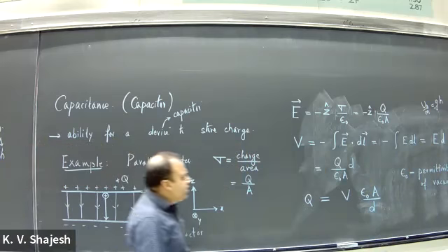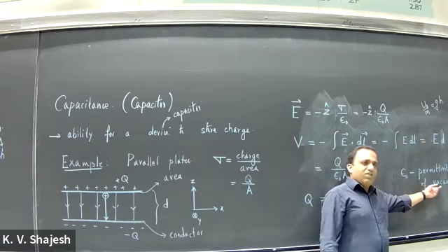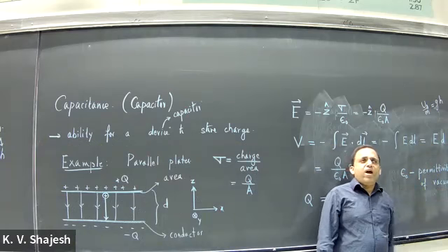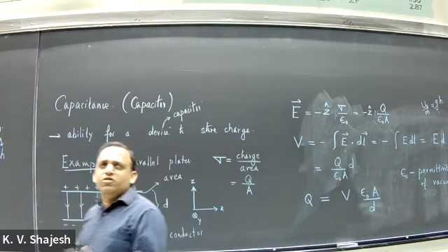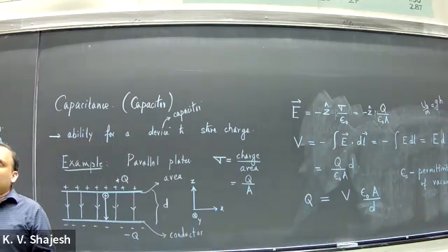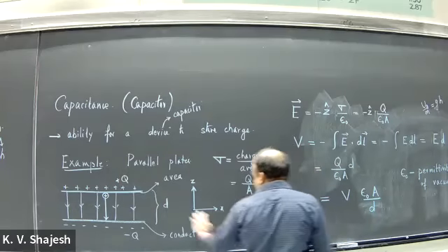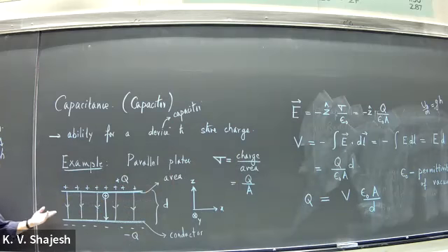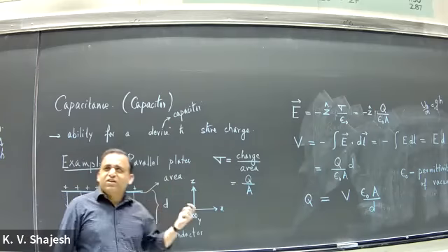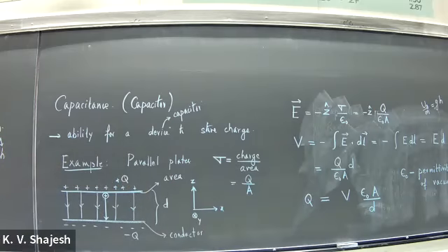Here we will actually give it some meaning. For now it is associated with the vacuum. In fact, that is a property called permittivity for any material. It will have to deal with how much polarization it can have, and we will talk more about it. So that is one more feature, that you can actually fill this with a medium. Typically, you don't want to have liquid, but there are capacitors with liquids in it. If you have a liquid, you can have larger capacitance. That is the advantage, but then it is harder to manage. Right? You need to have a better way to seal it.